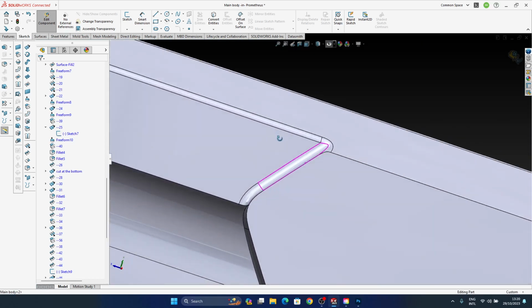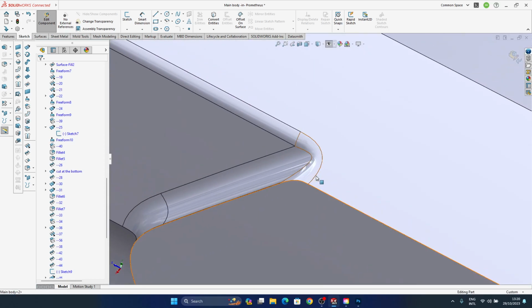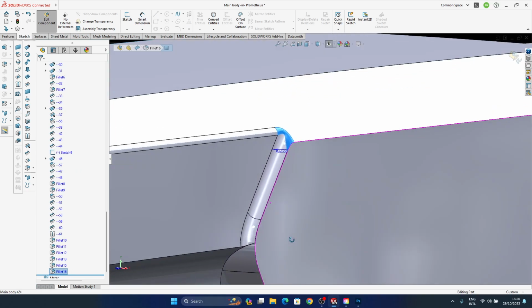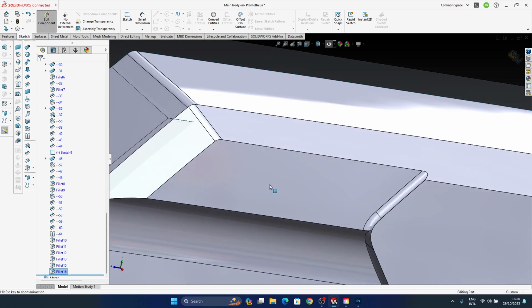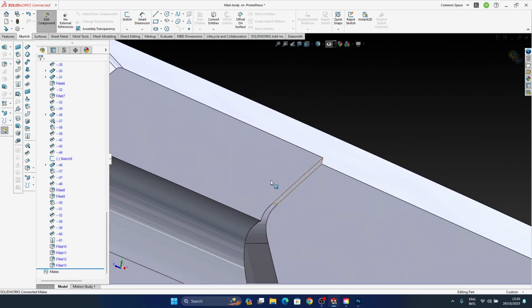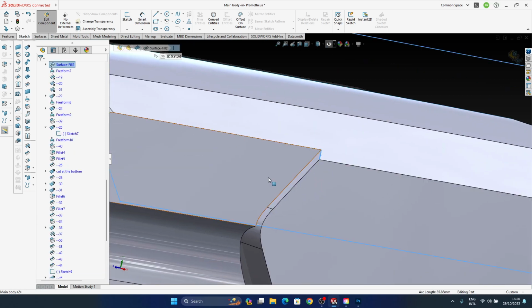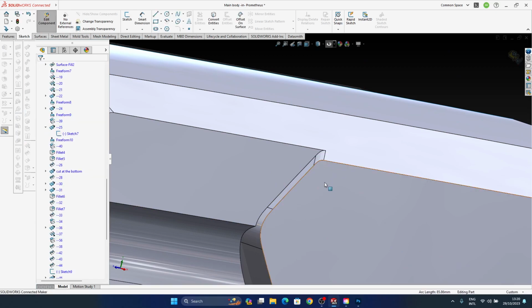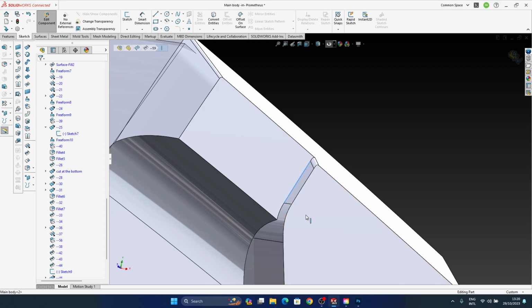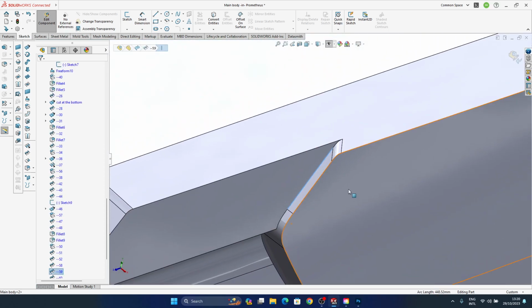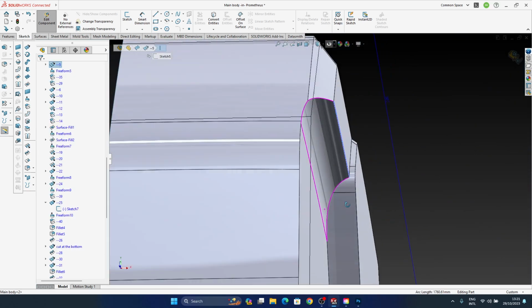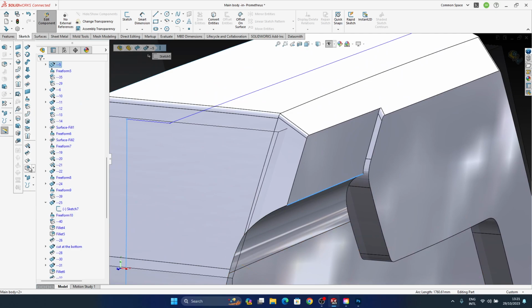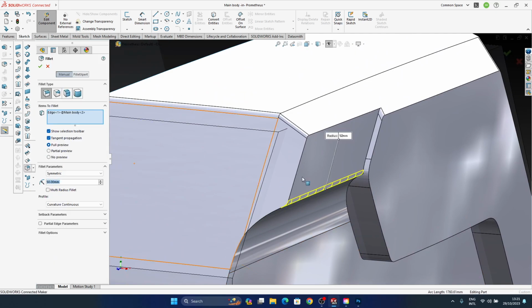And you see, I don't quite like the way it goes in here. I would say based on experience, in this case, it may not be so important, but I have a way of doing the fillets, of going through first the edges of the shapes and then building the ones that are at the base of the shape, for example. Anyway, in here I will need probably the same amount of fillet, like 50.